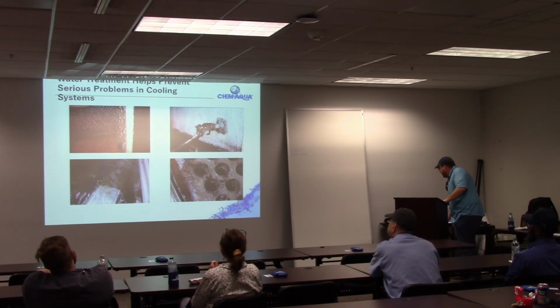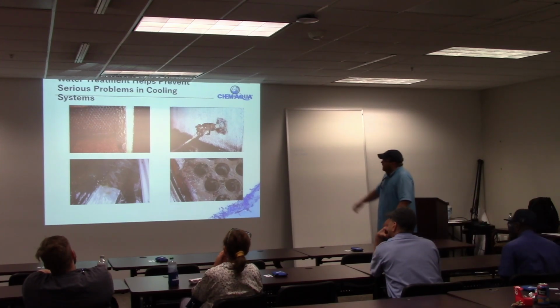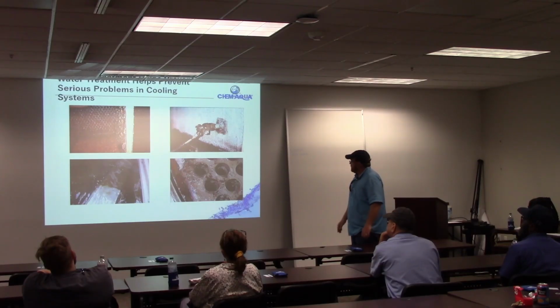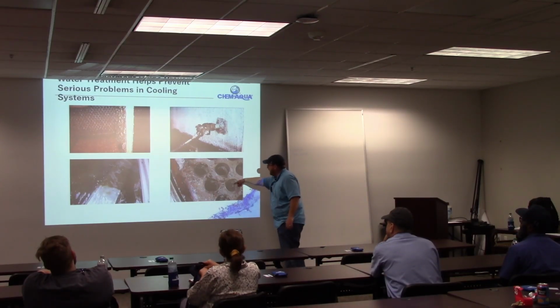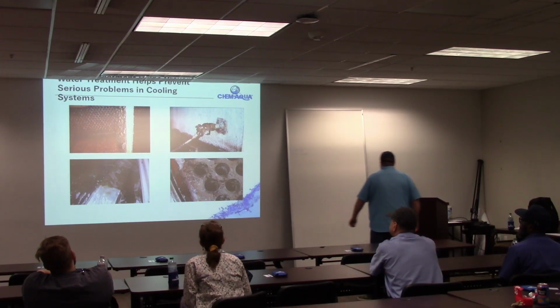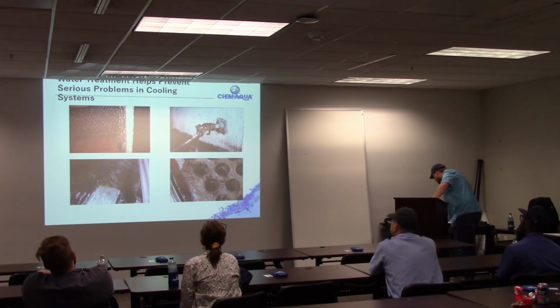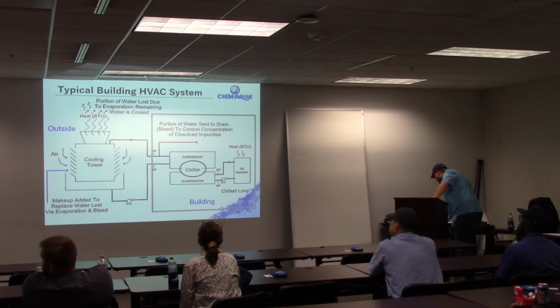All right, so we got a few things here. You've got some pretty bad corrosion issues over there on those condenser tubes. It's kind of hard to see, but we have a little bit of scaling and biofouling on these tubes as well as the tube sheet.